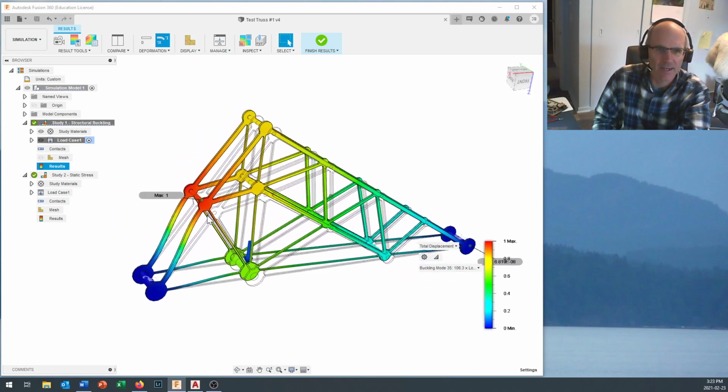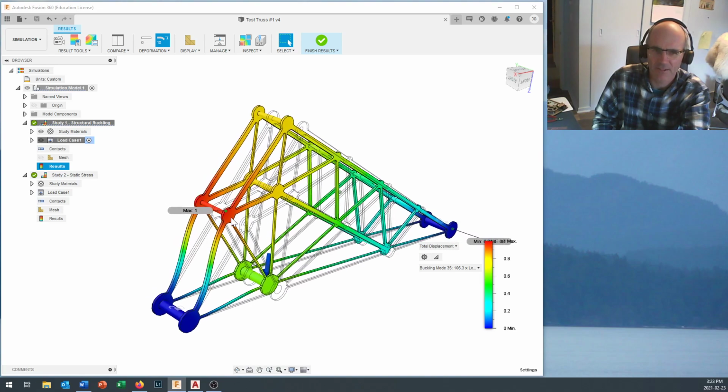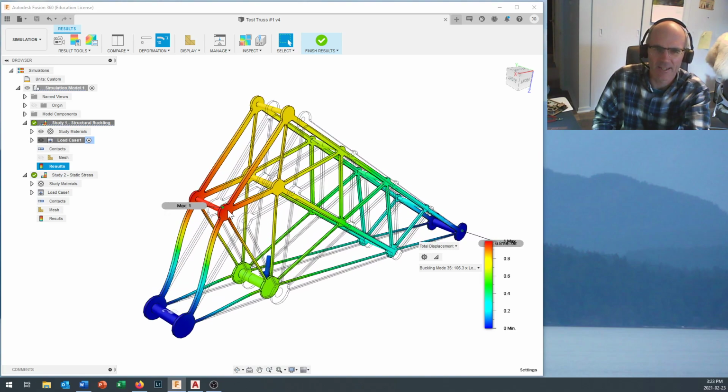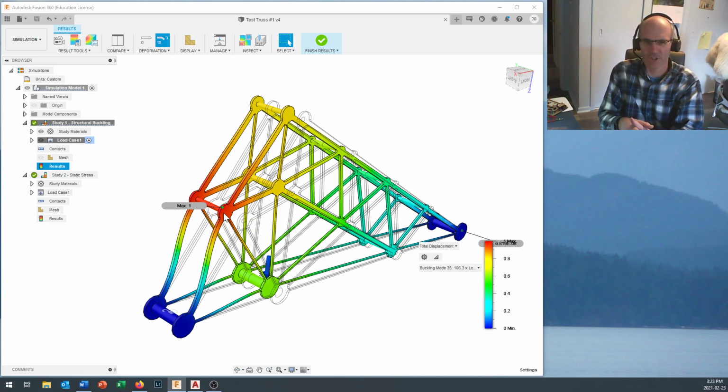Okay, I can also see that I wasn't really suffering too much from buckling in there, but right back here at the very back, as I predicted by hand, you can see that I've got a failure coming in right here. And if my hand predictions and my understanding of the structure jibe with what the computer is telling me, then that probably means that I can reduce some of the material out here, shift it back over to here, and use my 75 grams to create a stronger structure.